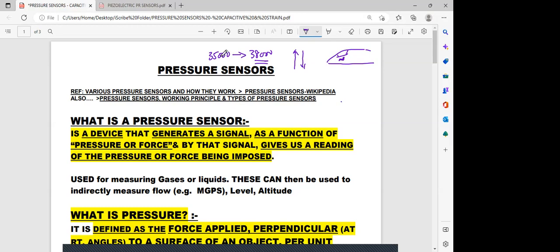So the pilots were giving this, the co-pilots were giving this. And the co-pilot didn't even notice. Okay, so this guy started putting the nose up. The plane was put up like that, started to climb. In other words, it went into a stall. And then once it goes into a stall, you cannot generally control the aircraft. It just nosedived into the ocean.